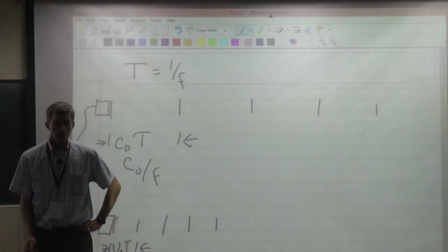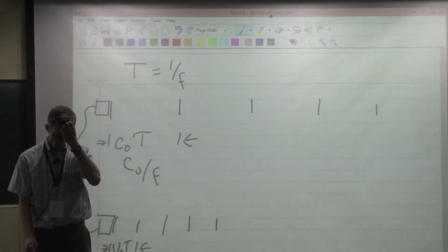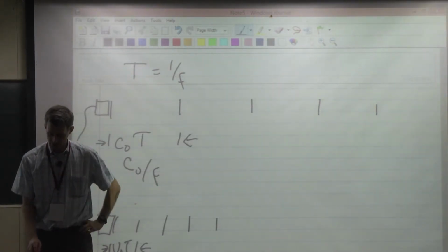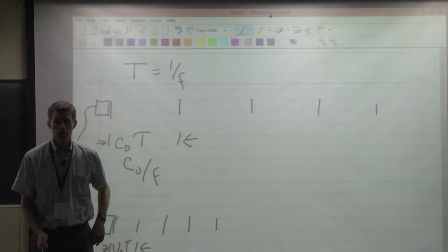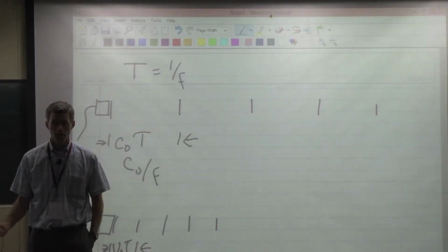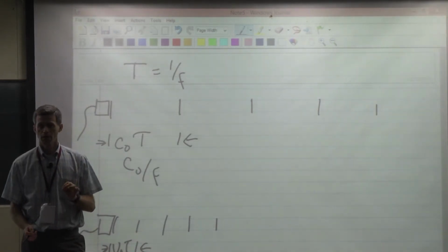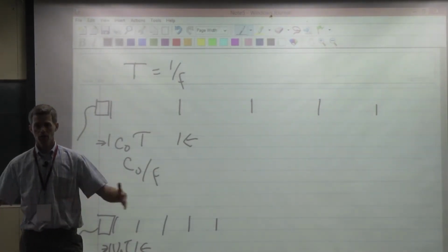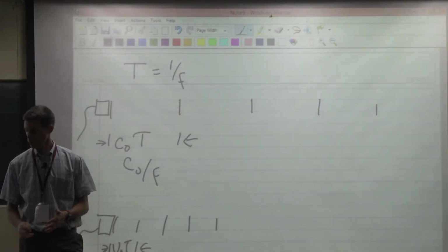In a low Mach number flow, u naught is going to be much smaller than c. That means that this convective wavelength is going to be a whole lot smaller than the acoustic wavelength. In fact, the ratio of these two wavelengths is the Mach number. So if the Mach number is 0.1, I have a problem with two very, very different length scales in it. The acoustic component has a long length scale, and the entropy and the vortical component have a short length scale, right?